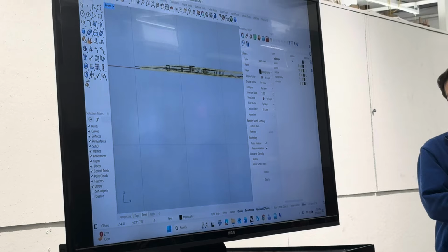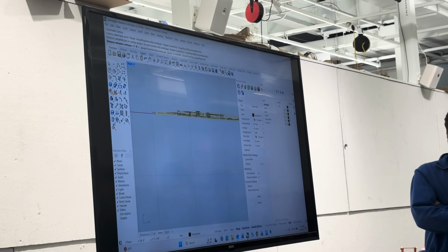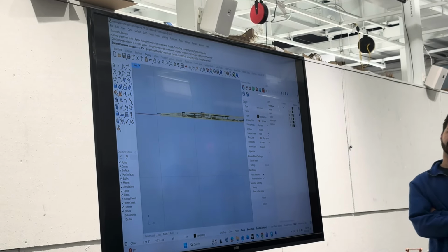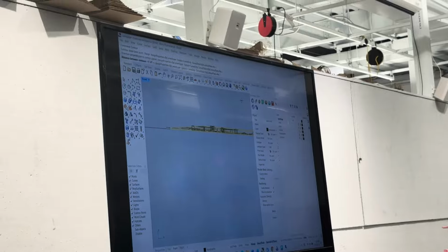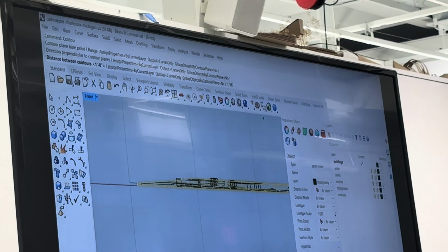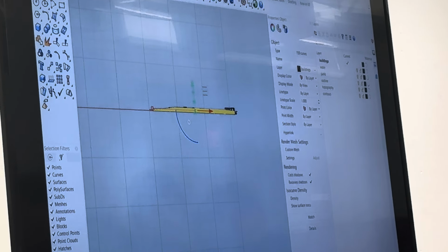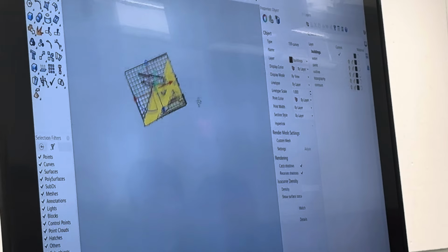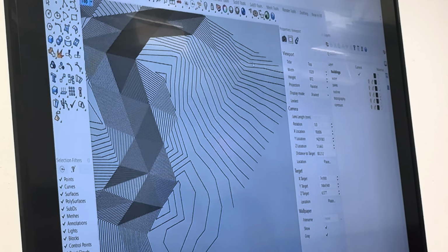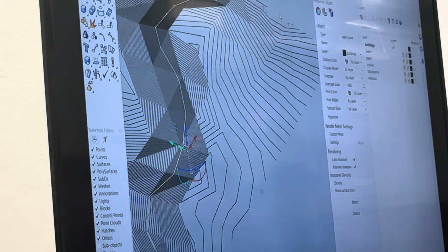Then I can tell the distance right now because it's at the top of the screen, and it's showing me that I'm going to be cutting at every foot, which I only want to be cutting at every 1/16 of an inch, right? So I type in the command line 1/16 of an inch. And it produces those cuts for me. Right? Oh wow. So I have each layer of chipboard that I would be making this model out of, right?